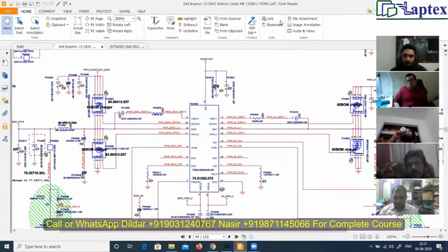In entry 1 it is 1.3 something like that, but in entry 2 it is 0. And that's wrong. Both should be 1.33 volt, 1.35 volt. Today you will understand how both will get that voltage. So did you isolate that point?